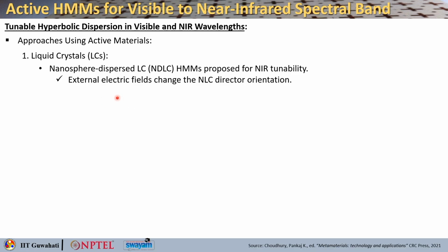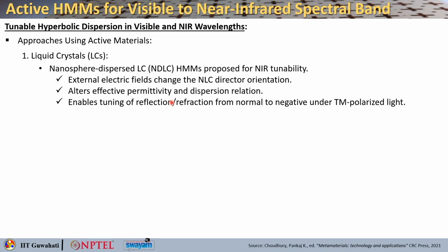In this, the external electric field can change the orientation of the liquid crystals, and that will change its optical property. So it alters the effective permittivity and also the dispersion relation, and it enables tuning of the reflection or refraction from normal to negative under TM polarized light.